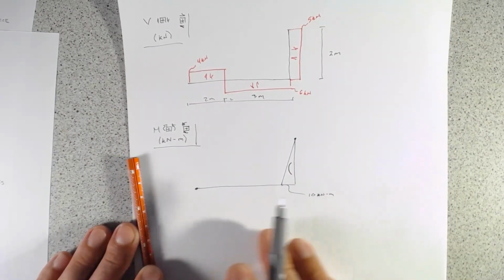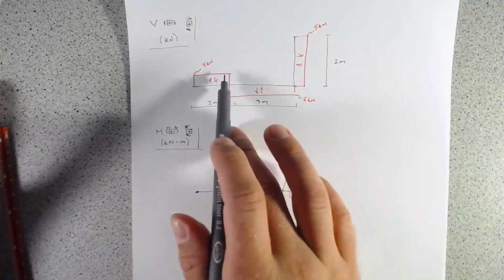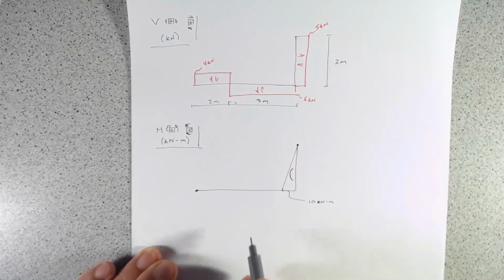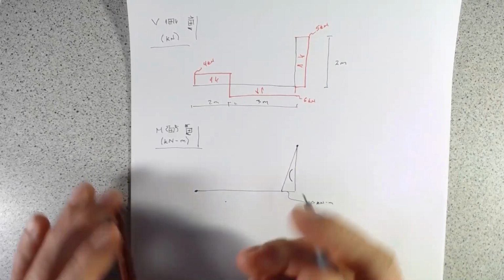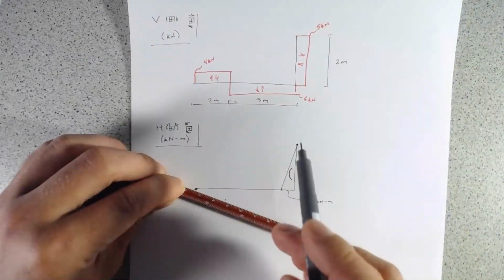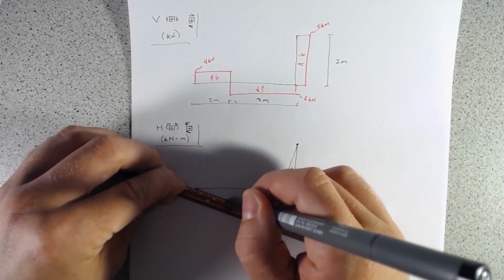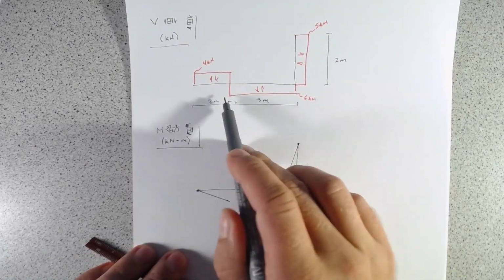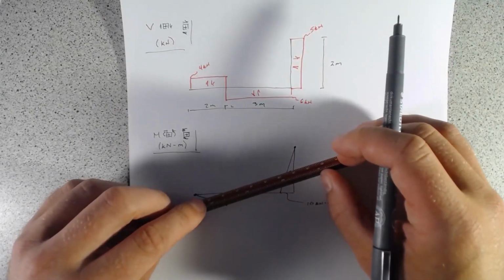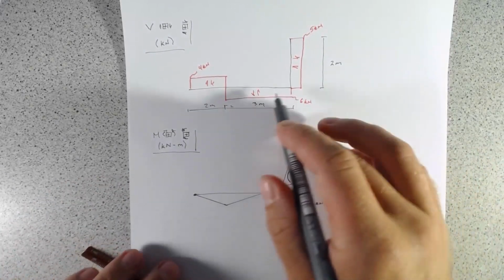Now, for the beam section, we can use our graphical rules from the shear force diagram, and we know that if we have, again, a constant shear, we're going to have a linear distribution of moment. And we know that we're pushing down, so we're going to bend the beam in a banana, and the tension side will be on the bottom. And we will go until we then change directions, and then we have a negative shear, and so we will change our slope. And if you remember, our slope is going to be opposite of what the shear force is.